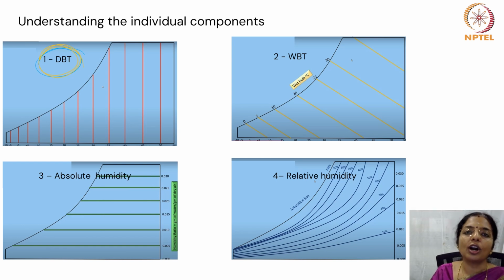It is called dry bulb because the thermometer is not influenced by the moisture content in the air. The important thing about dry bulb temperature is it is the most commonly used temperature measure and is crucial in determining comfort levels in the built environment, as well as in heating, ventilation, air conditioning design and performance analysis.